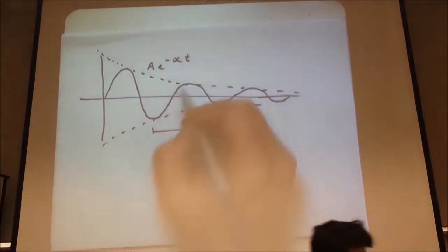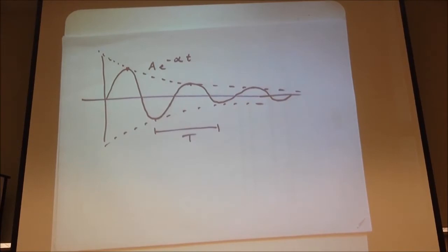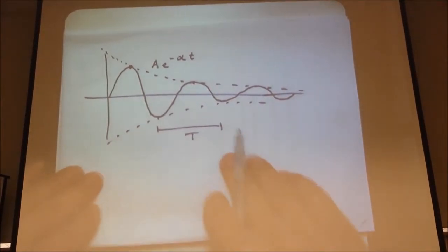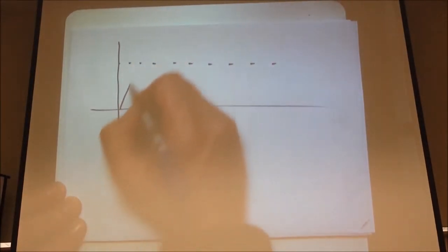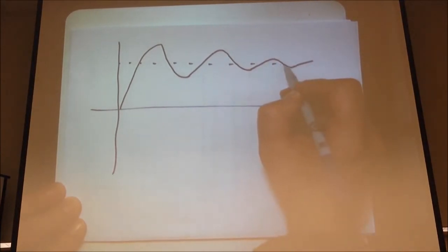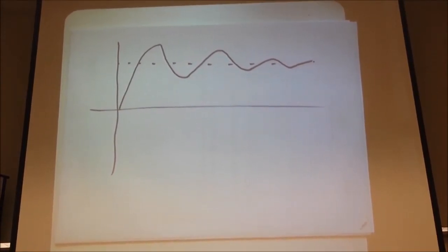You need 2 points and 2 unknowns. And we did that in last class, so hopefully you have a good feel for it. We saw it in the lab. One thing that bears mentioning, this is oscillating and settling about 0. This is an easy exponential fit. On the other hand, if we have something that has a DC offset, the reasoning is the same. So here's our t, and then here's our DC steady state term. And we have something that climbs up and maybe does this. And this is what you kind of saw with the current. And that's exponentially converging to the DC steady state value instead of 0.